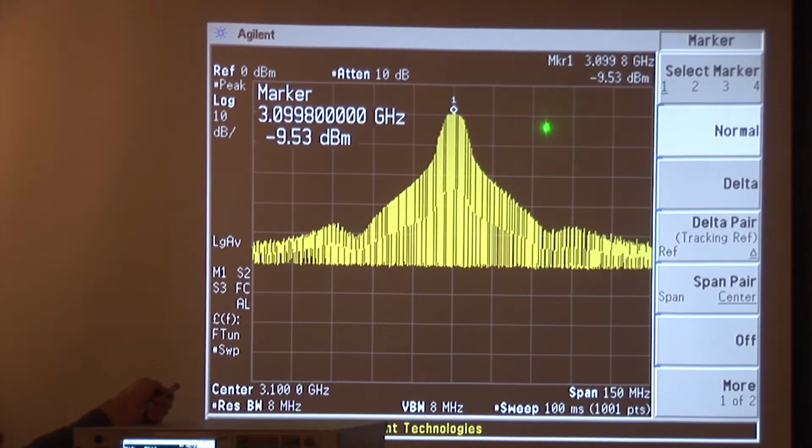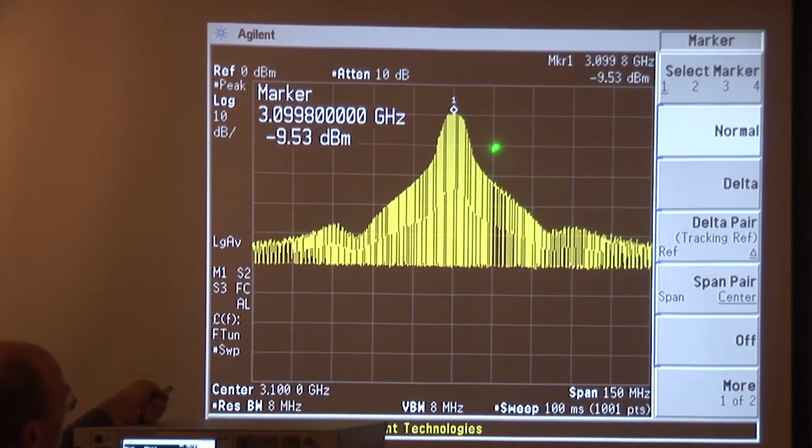I've actually programmed it to put out a total of minus 10 dBm of power. And so you notice that although that minus 10 dBm of power is spread across this whole frequency range, we're actually hitting minus 10 dBm right at the fundamental, because these power levels are 10 dB, 20, 30, 40, 50 dB down. Well, 10 dB is a tenth of the power, 20 dB is a hundredth of the power, a thousandth of the power, a 10,000th of the power.